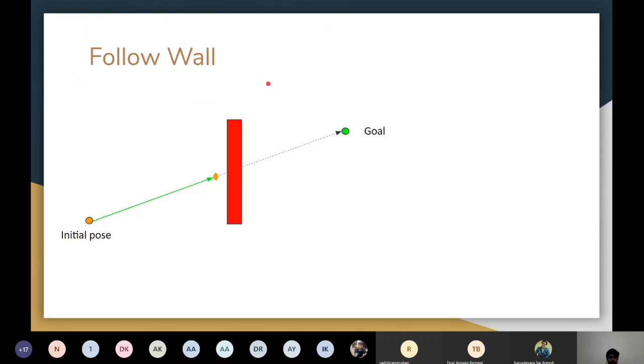We have seen go to goal and avoid obstacle behavior, but now comes following of the wall. So what we do in such a scenario is that once such an obstacle is detected, instead of avoiding it, we'll start to follow that particular thing. And we will avoid the obstacle only when we have reached a further distance into the obstacle. We'll cover later what to choose, follow wall or avoid obstacle, in such a scenario, through our diagram. But first, let's see what follow wall behavior is.